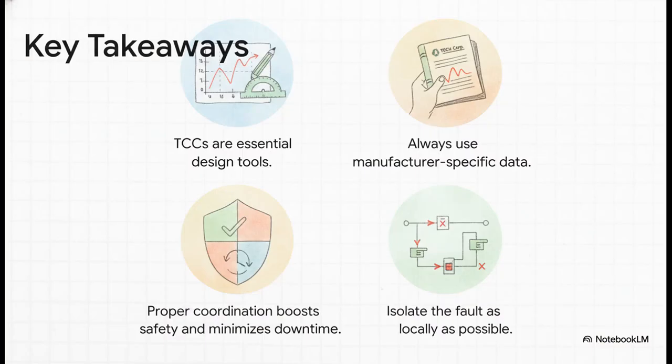All right, we have covered a ton of ground, so let's just boil it all down to the absolute key takeaways you need to remember. First, TCCs are not just pictures. They are fundamental design tools. Second, never guess. Always use the specific TCC datasheet from the manufacturer for the exact model of the device you're using. Third, remember that all this work has two goals: increase safety and minimize downtime. And finally, it all comes back to that golden rule. Your number one job is to isolate the fault to the smallest possible part of the system.